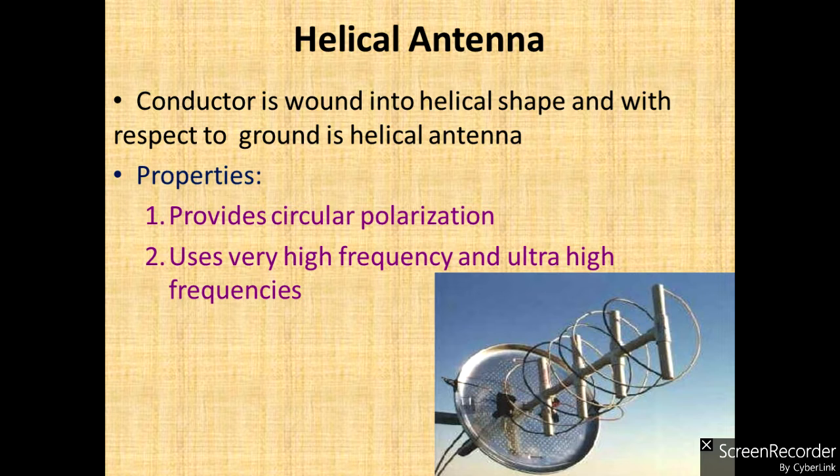Now the conductor. As I told you, we can make a helical antenna by a conductor wire. So the helical shape of that particular antenna will be acting like an antenna, right? And one end of the antenna can be given to the ground, and the other part can be left as such, so that the radiation can be maintained